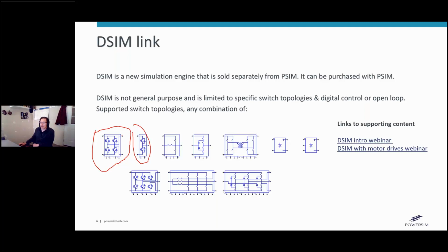I have an example that has a 10-unit MMC with 120 active switches, with 10 inverters using them, so 1,200 active switches. Or you can go H-bridge chopper style and build up something that way. It's a single phase system. So definitely there's lots of strong support for MMC with PSIM. So to answer that question.